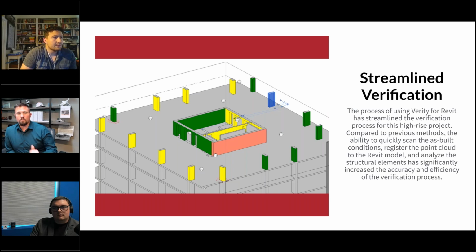And we tie those to the Revit model. We put our Revit model on a shared coordinate system with those same northings, eastings, and elevations. That way, all the points of my point cloud have a known northing, easting, and elevation that aligns with my Revit model. So once we link them, there's no trying to align.